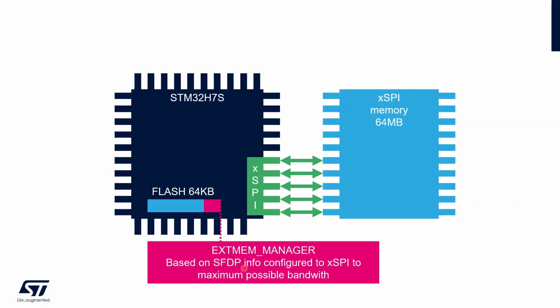But of course, the prerequisite is that this memory has the SFDP protocol. Usually they announce it inside their datasheet. In case you don't have a memory with this protocol, you need to create this driver by yourself, which is more complicated, which I will show you inside exercise number 2.